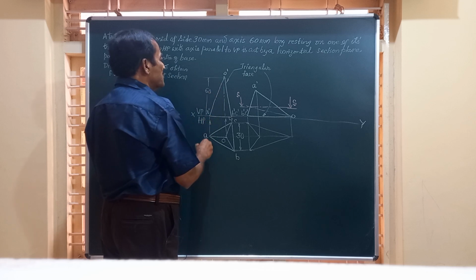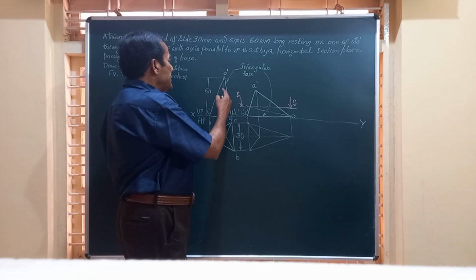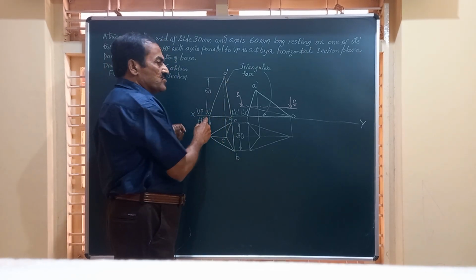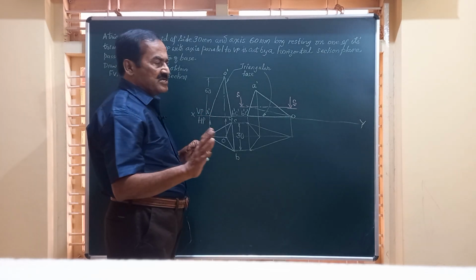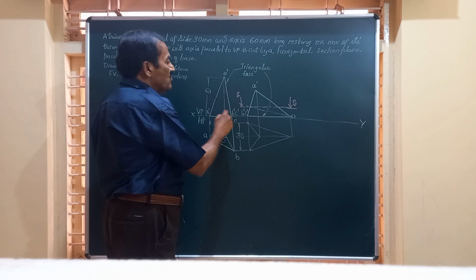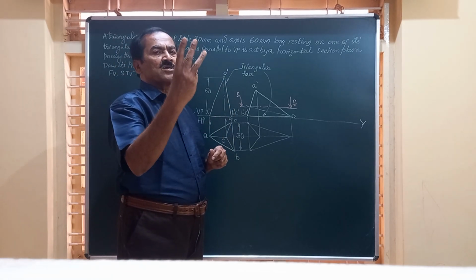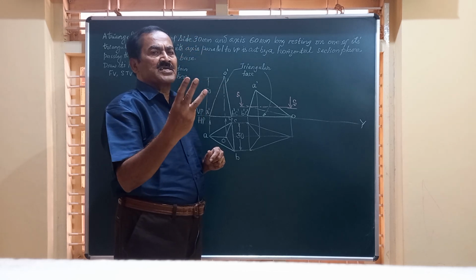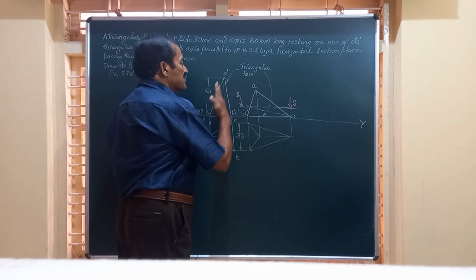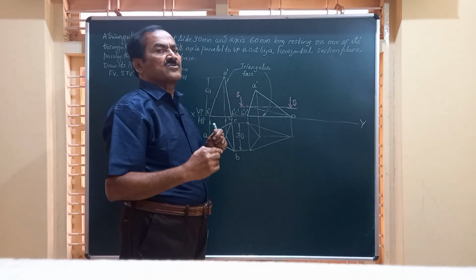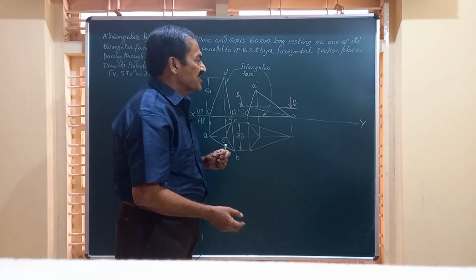And friends, if you observe the front view of the pyramid, the line O dash A dash to the left of you represents a slant edge, whereas this line O dash B dash C dash, which has got 3 points OB, OC and BC, represents a triangular surface, and this triangular surface is at an angle to HP. But as per the problem, it has to be on HP.